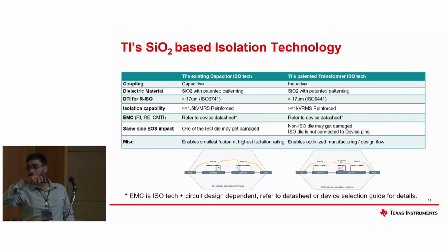Now this design and this design become independent of this. You only need to bond the two dies from each side to the isolation die, and the high voltage protection and ratings are taken care of by this, and of course the lead frame, which is also designed for that. For every device you need not go through the high voltage qualification and reliability, which goes on for months.